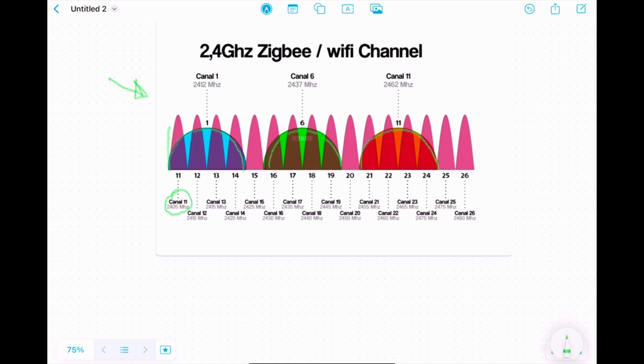And we have Zigbee channels, which are the pink ones. Now it's recommended to use channels 15, 20, and 25, 26 of Zigbee because, as you can see, they do not interfere with these popular channels within Wi-Fi. But our project is going to focus on minimizing the interference by being able to identify the patterns in Zigbee and Wi-Fi from their spectrogram image, and being able to classify these two signals.